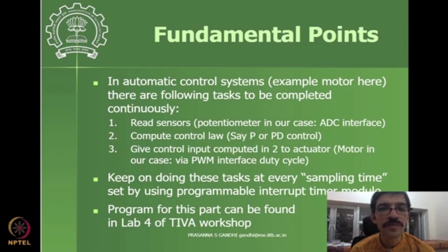For them to be executed every sampling time, a pulse needs to come on the pin at every sampling instant. Typically these pulses are generated by a timer module. The counter timer module has the job of generating this kind of pulse at every sampling instance, and this pulse is internally connected.